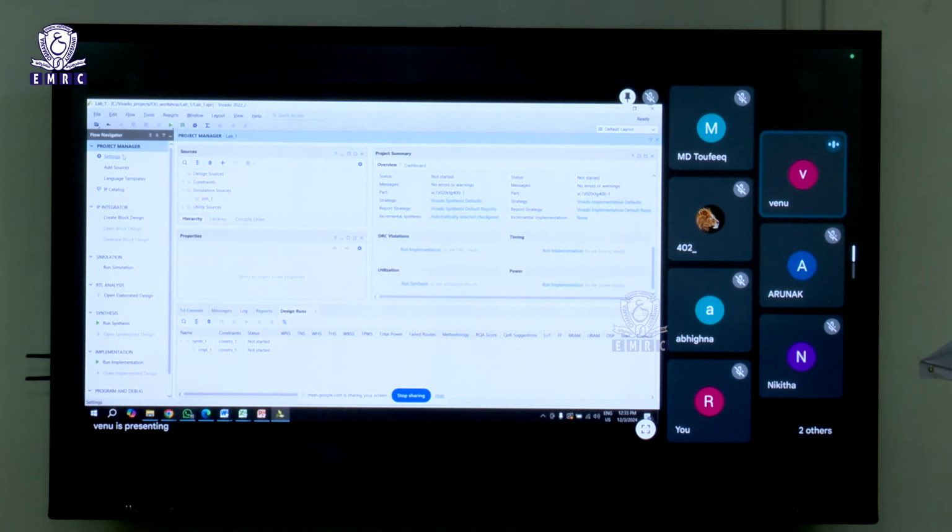Why do we call them lookup tables? We have an AND gate. We all know the functionality of an AND, but we cannot replicate an AND gate directly on the FPGA. Then how is it working? How is an AND function happening on the FPGA?